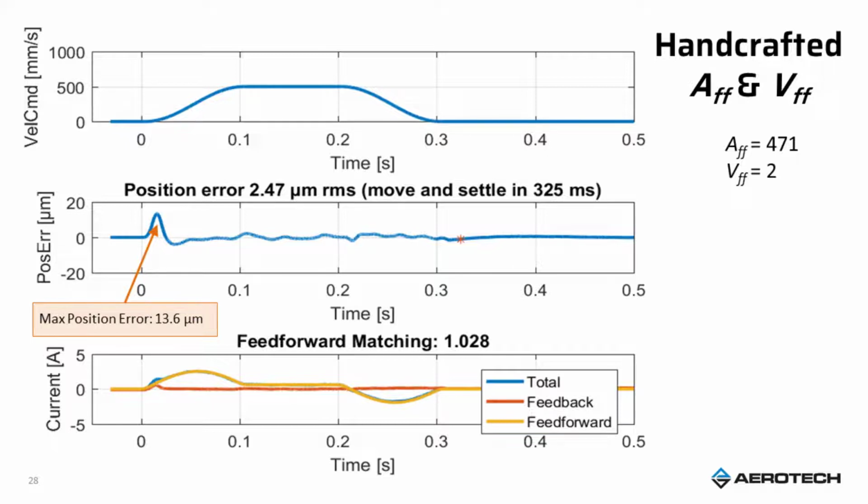The tuning algorithms tend to look at multiple facets and different move types. So you might be better off, if you're looking for robustness, just to stick with the Autotune. But if you have one specific move that your machine's making over and over and over, a little handcrafting by looking at all these different tools that I've shown you might be the best way to go.